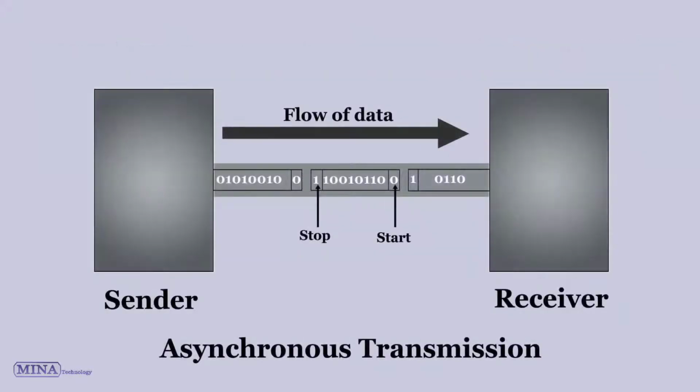USART asynchronous mode. In this mode, the USART uses the standard non-return to zero (NRZ) format: 1 start bit, 8 or 9 data bits, and 1 stop bit. The most common data format is 8-bit. An on-chip dedicated 8-bit baud rate generator can be used to derive standard baud rate frequencies from the oscillator. The USART transmits and receives the LSB first. The transmitter and receiver are functionally independent, but they use the same data format and baud rate.